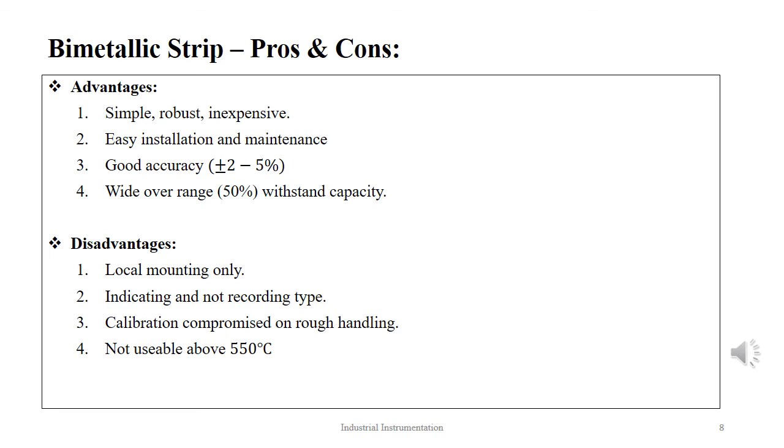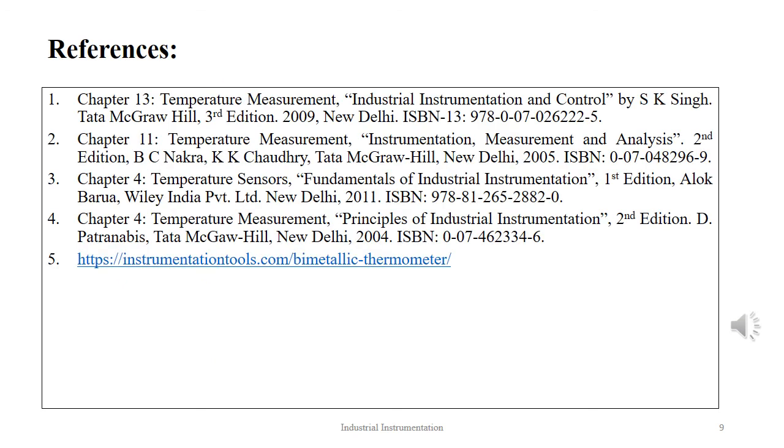The limitations of this device are that it only supports local mounting, it is only of indicating type and not of integrating or recording type. The device calibration is affected upon rough handling, and the device is not suitable for temperature measurement over 500 degrees Celsius.